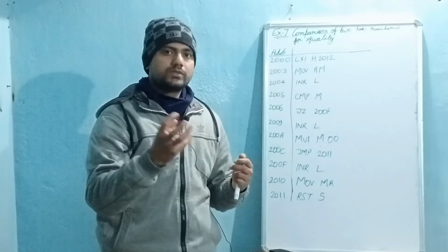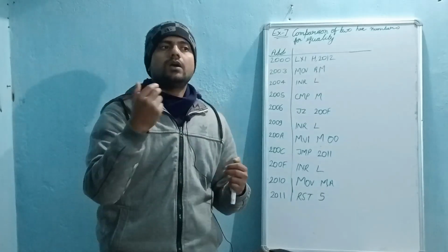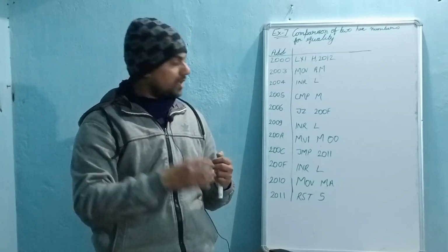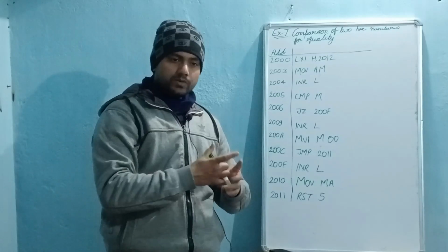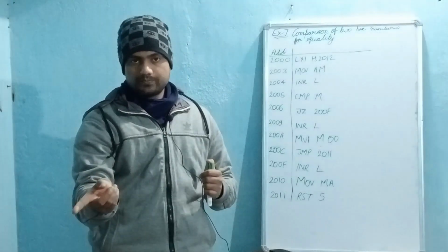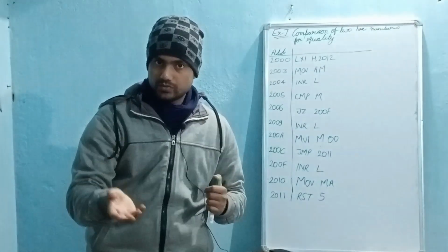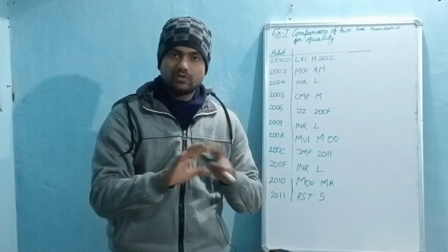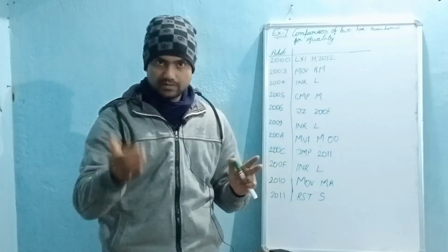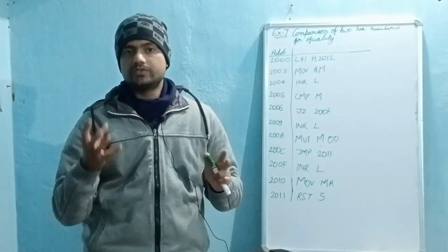The microprocessor will check whether those two numbers at those two memory locations are equal or not. If those two numbers are equal, then that number will come in the output, at the memory address where we check the result. If those two numbers are not equal, then at the memory location where we get the result, we will get 00.